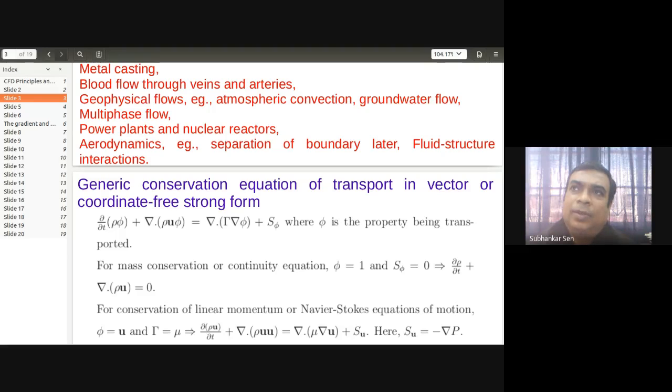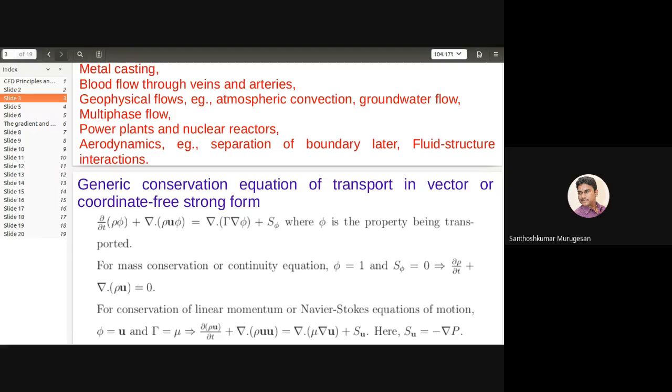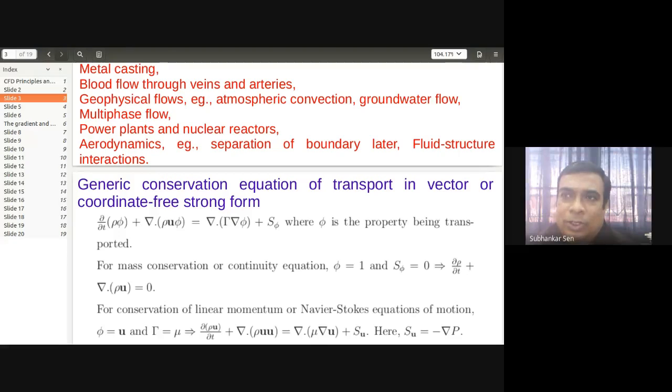Most of the flows which we come across are turbulent in nature and three-dimensional in nature. If we go for high Reynolds number laminar flow or turbulent flow, these convective terms are never zero. It means that we cannot solve this equation by direct integration. So this analytical approach is not possible to implement for real life fluid dynamics problems. Ultimately we have to find a different approach where we can get very reliable, highly accurate solutions, quick solutions, and without much complicacy.